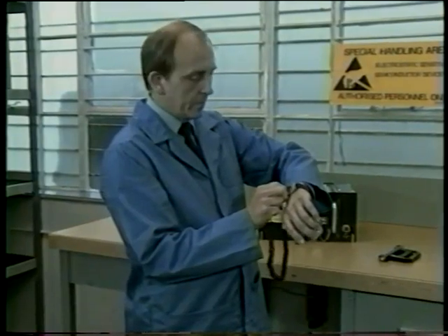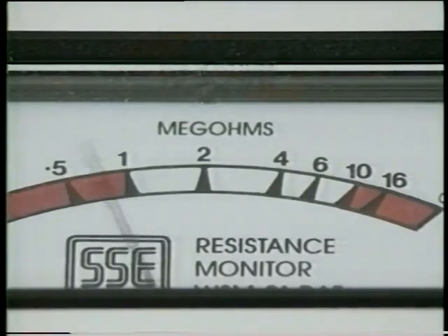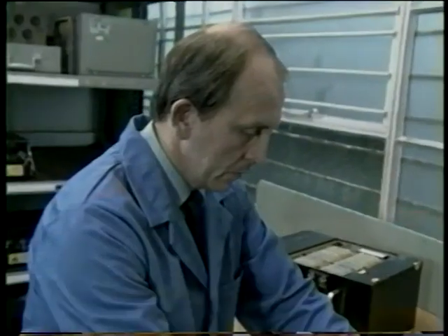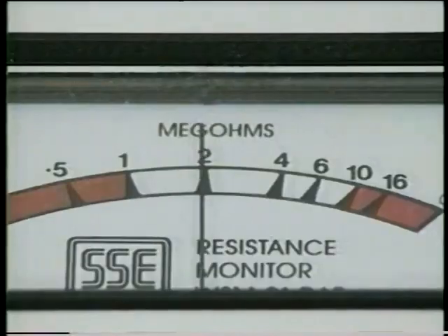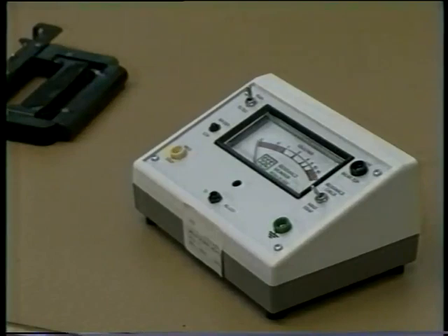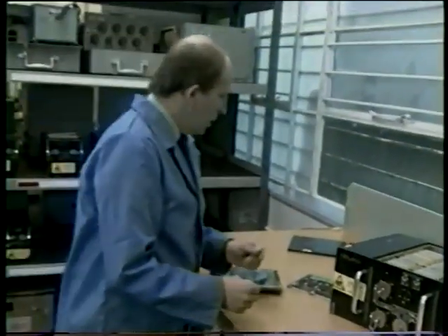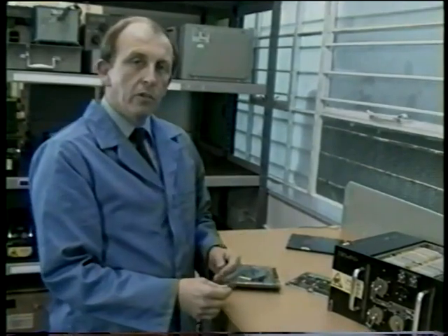Okay. The integrity of both the grounding connection and 1 megohm protection resistor must be confirmed by using the wrist strap monitor every time before use. This ensures the safety of both the operator and the equipment. The wrist strap should be tested after finishing as well to confirm that the work was safely completed. Are there any other pre-use checks?